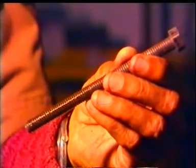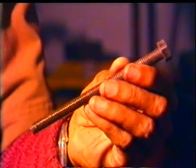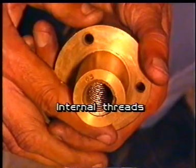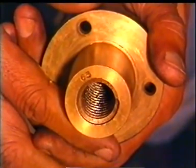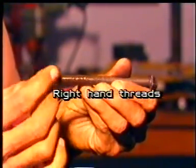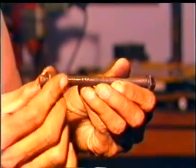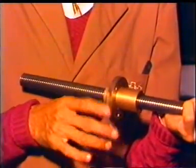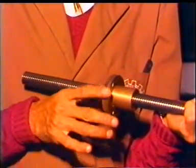External thread is a thread on the outer surface of a part, whereas an internal thread is a thread on the inside of a part. A right-hand thread, when assembled with a fixed mating thread and turned clockwise, moves away from the operator, while a left-hand thread, when turned clockwise on a fixed thread, approaches the operator.